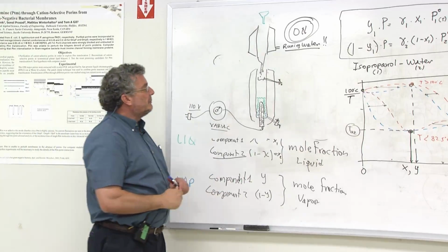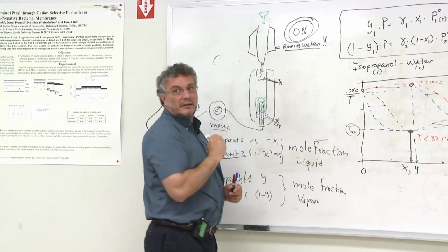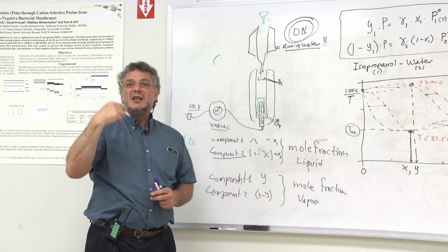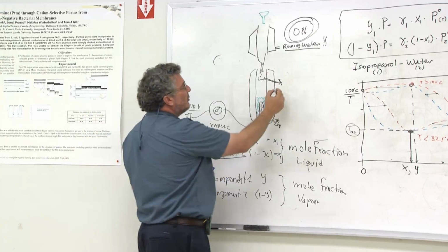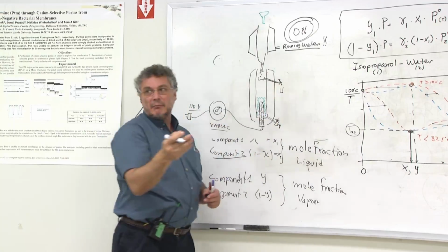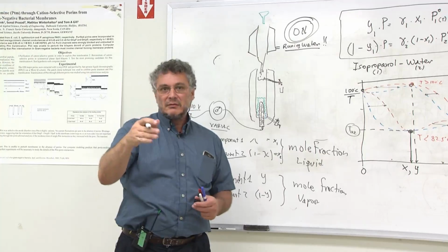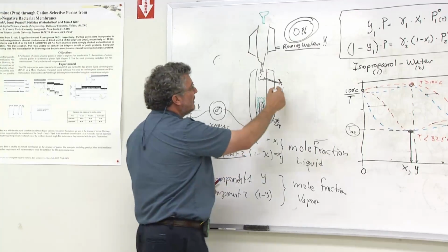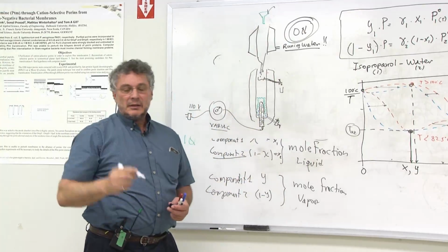And you have to remember that when you change samples, some of the old sample gets stuck here, and also some of the initial value before you reach equilibrium. So you might want to drain this before actually sampling. Don't take just the first bit that goes out. Get out some of the material, you take it out, and you can either return it to the system or you can throw it away.